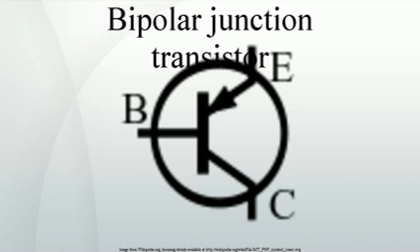Transistors can be thought of as two diodes, PN junctions, sharing a common region that minority carriers can move through. A PNP BJT will function like two diodes that share an N-type cathode region, and the NPN like two diodes sharing a P-type anode region. Connecting two diodes with wires will not make a transistor, since minority carriers will not be able to get from one PN junction to the other through the wire.